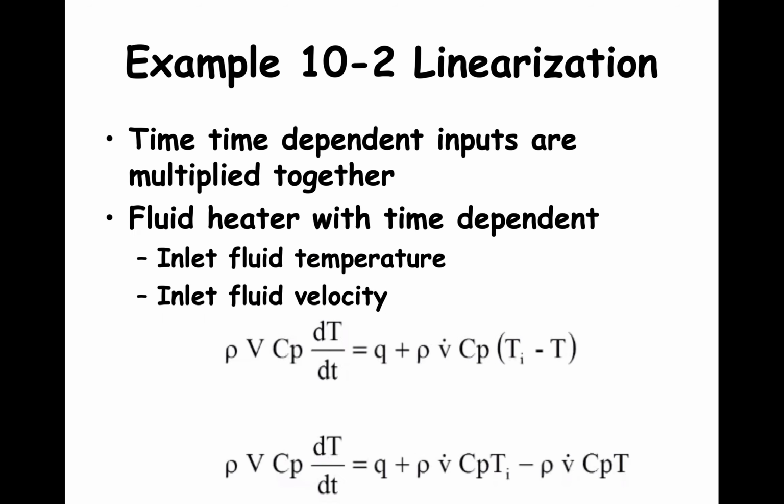There is another common type of problem for which we need to use the Taylor series expansion to linearize part of the equation so that we can use Laplace transform to solve the problem. The problem is when two time-dependent inputs are multiplied together. We have avoided that situation before by assuming only one input could vary. But in reality, several inputs could vary, and if we want to analyze the problem with two or more varying inputs and they are multiplied together in differential equations, we will end up with a nonlinear term.